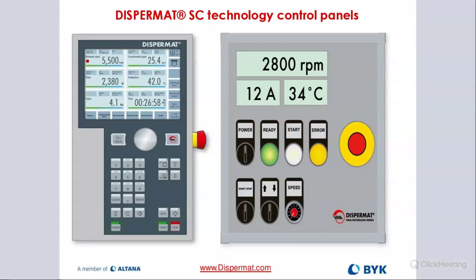Temperature readout right there in the middle, 42C. We can change that to Fahrenheit, and then we have a timer function as well. Now with the C technology, I'm able to also program what is called cutoff values. That means if I have a product, let's say that's temperature sensitive, and you don't want it to exceed a certain temperature point, then you can program it where, let's say, 80C would be our cutoff. Then I want to be warned at 70C, and then I want to get a second warning at 75C. So I can program that. And then at 80C, the machine would either cut off or run with a different speed or different energy input.